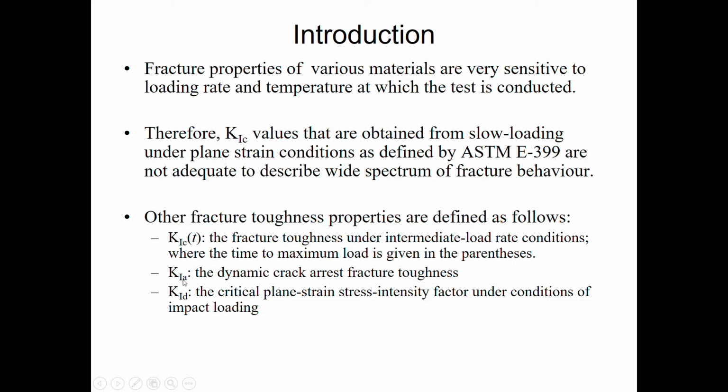Okay, K1a, the dynamic crack arrest. A here is referring to the arrest fracture toughness, while the last one is K1D, the critical plane strain stress intensity factor under conditions of impact loading, which is very rapid motion.